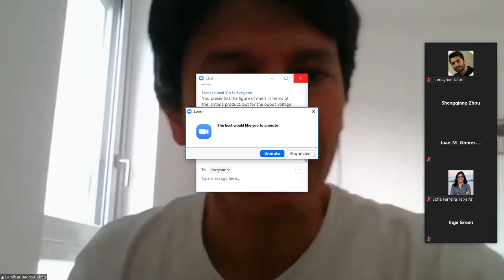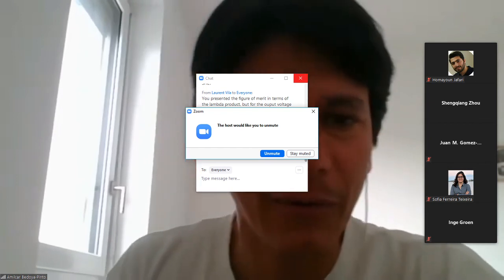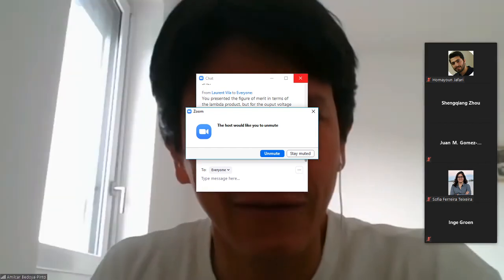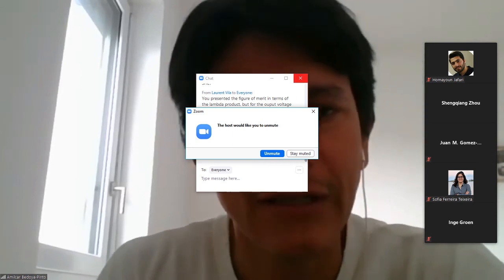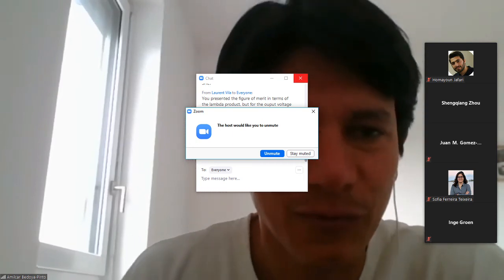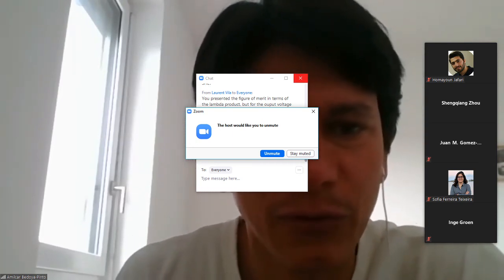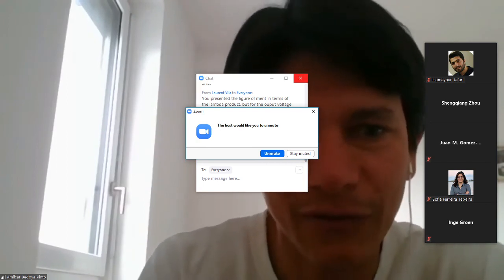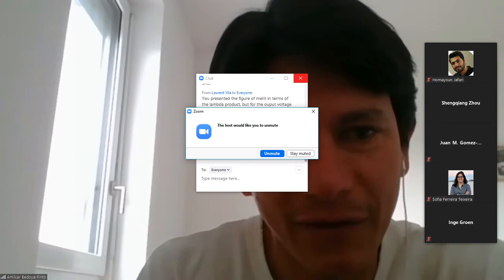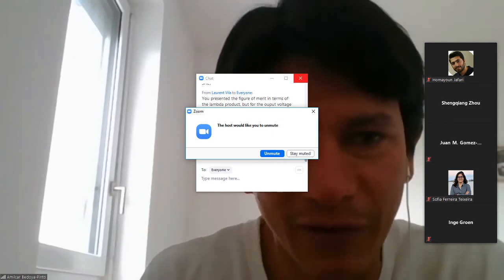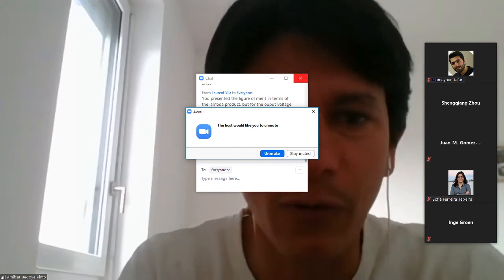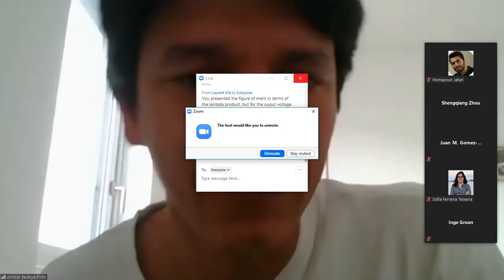Okay. So maybe I can elaborate directly what I mean. Usually in this part, when you have the proximitized graphene, you will have this spin to charge conversion, but you also have spins that flow through the graphene. You will have a region where you have the conversion, and you will have already converted charges that flow across the T junction.